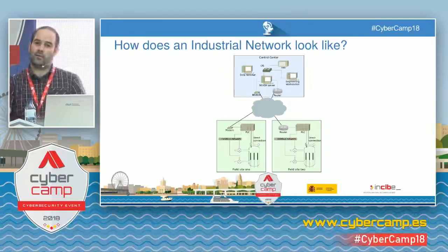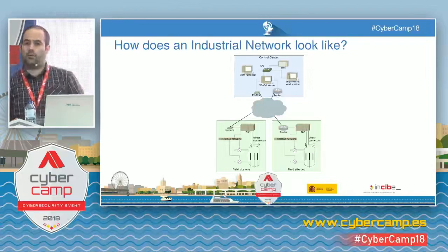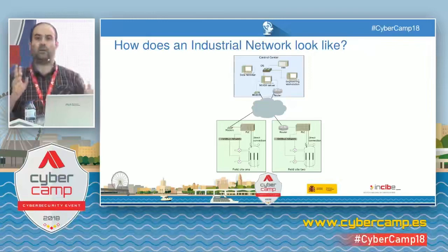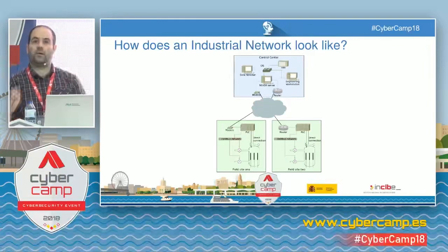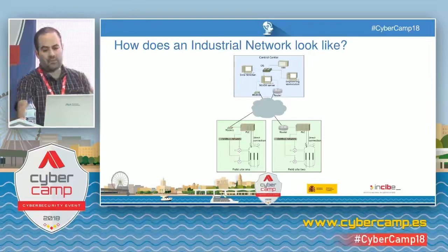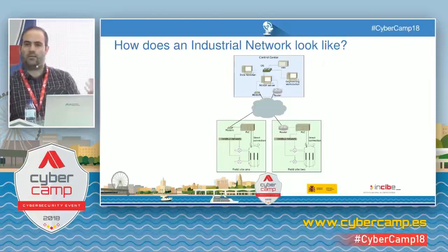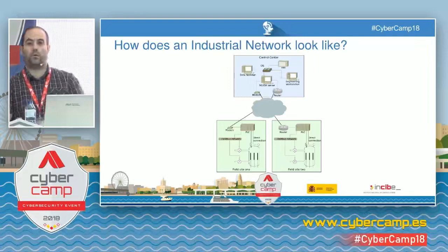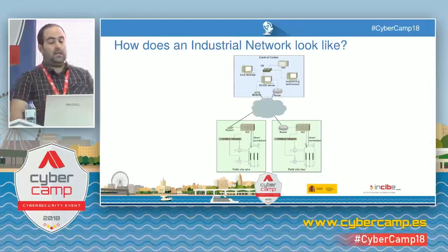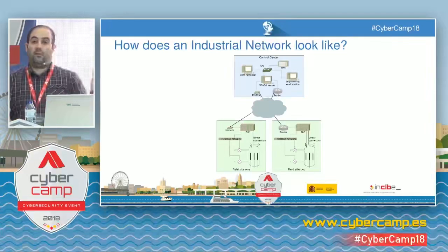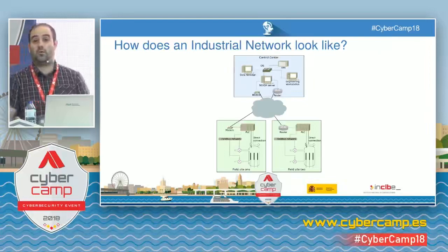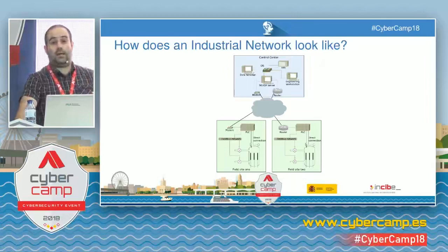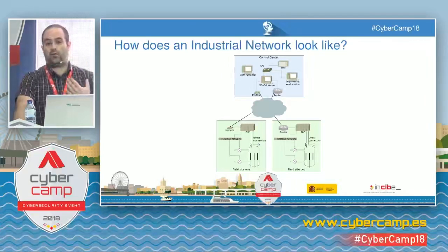We will see that the main control systems in industrial environments are PLCs. What other control systems would we have there? Over and above that, in the same layer, we would have the SCADA controllers. It's like the supervising layer, because we have controllers down below in charge of less important tasks, and then the higher layer in charge of the more advanced controls. Then we have data historians gathering and recording all that information so that it's available for whoever needs it, whether it is to keep an inventory or whatever. And then we would have the human-machine interface, HMI, checking that the process is working on a higher layer.